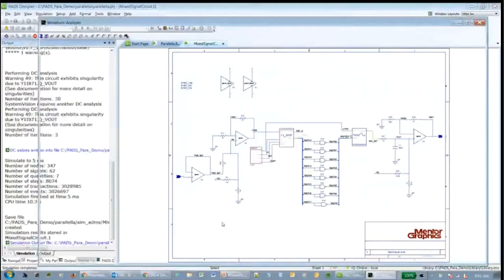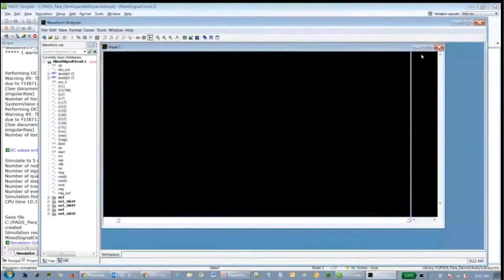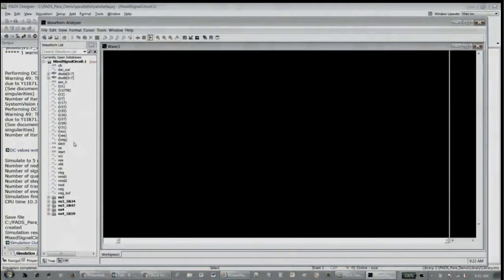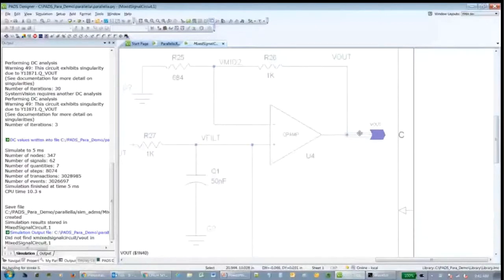And I'll just show a little bit of interaction between the schematic and the PCB. If I've got the simulation results, I can see the results here, and I can click on nodes to understand the schematic a lot more, and it's easier for me to probe from within here. I can select a net and say plot waveform, and now when I go over to that, it should have... Well, that's not working, but that should have launched, selected my signal here, and opened it up for me.